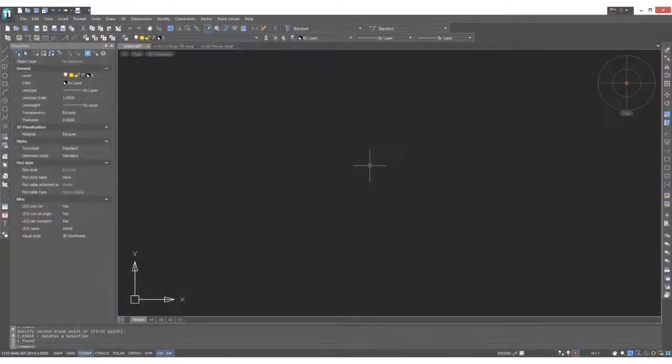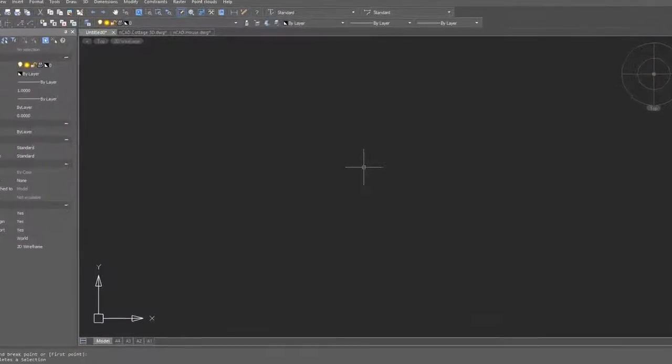Placing an arc in exactly the right position can be difficult enough that CAD users have found workarounds. One of them is to draw a circle and then remove the part you don't need to turn it into an arc. Here I'm using the break command. I pick the start of the arc and the end of the arc. nanoCAD removes the part I don't need.